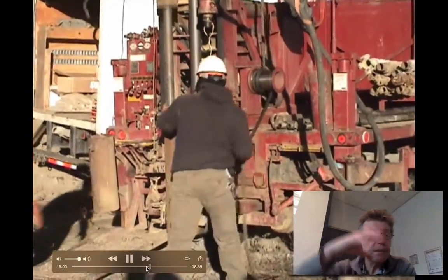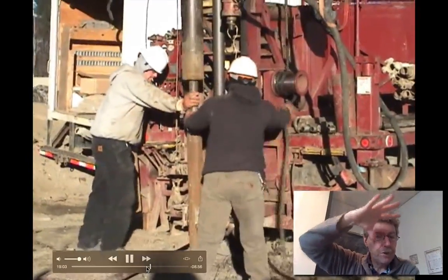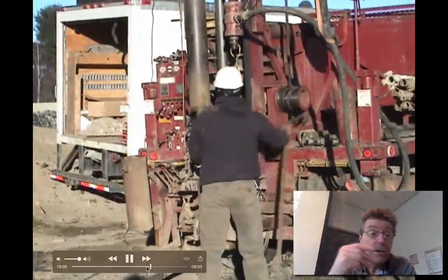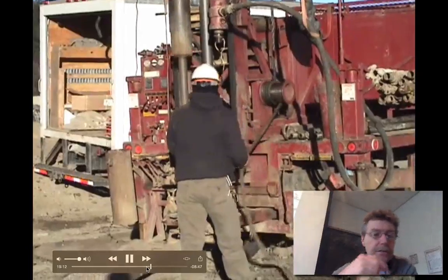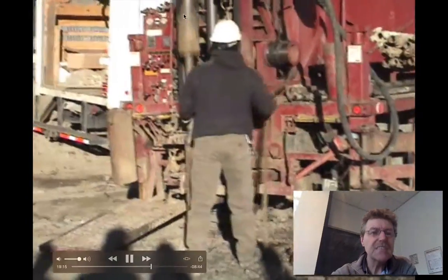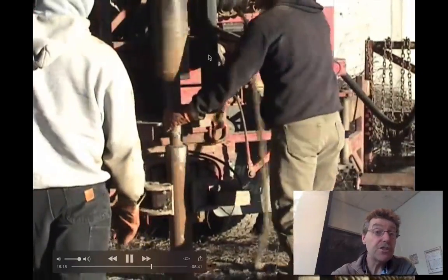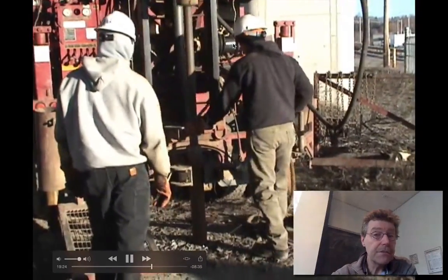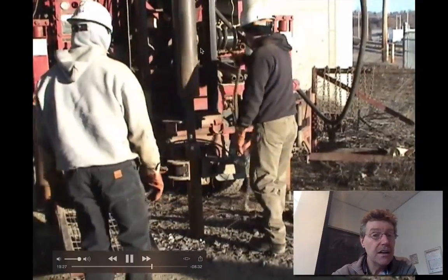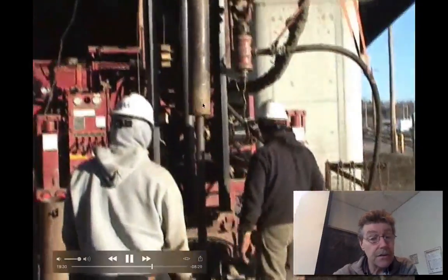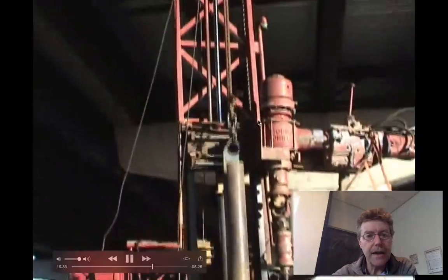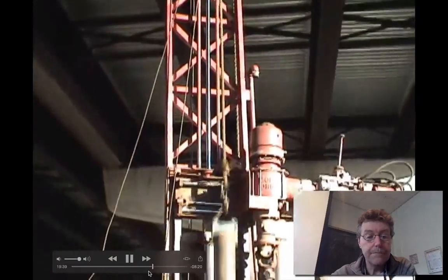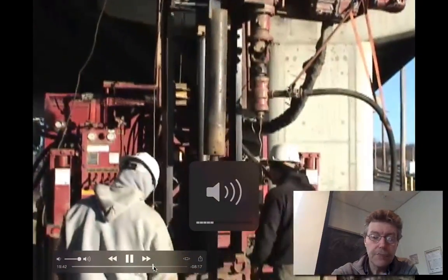But instead of being able to physically put the drill turntable on top of it and push it into the bottom of the borehole, you use a monkey hammer. I don't know why it's called a monkey hammer, but you can see it's a cylinder of a standard weight that's raised up a certain height and then free dropped. A couple of loops around a capstan. You pull it tight. It gives enough friction to raise the hammer. And then it drops down, and physically it's banging this thing into the ground. I think here it's just banging casing. It doesn't look to me like it's banging a tool into the ground, but it'd be exactly the same mechanism that you'd use to do that. And you can hear the ring, of course.